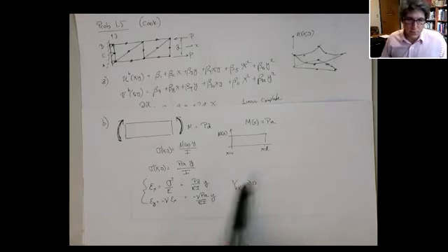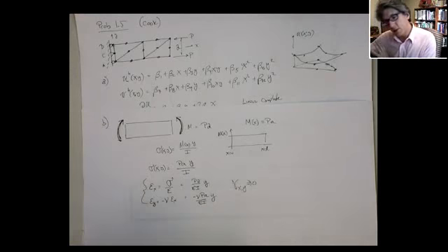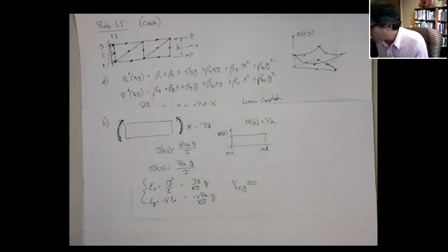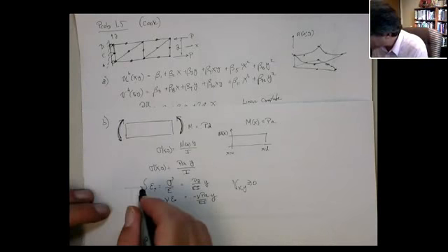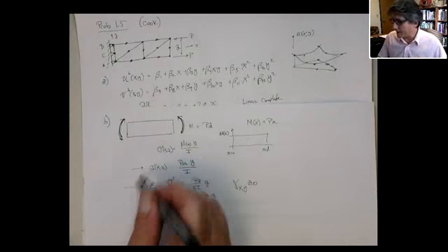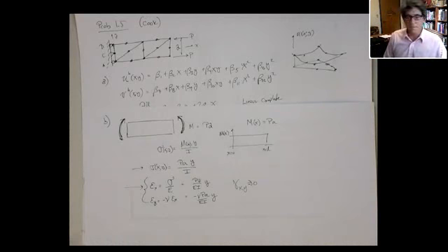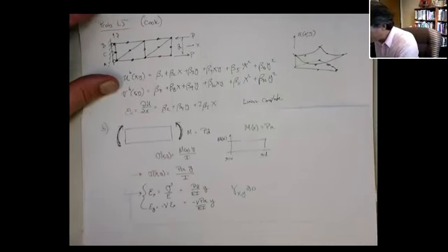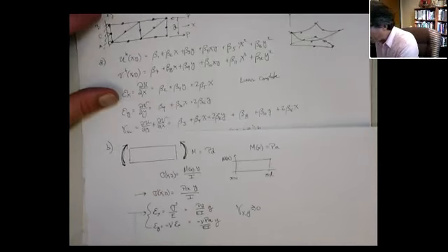That will be a little difficult to show up, but let's talk about a situation where the shear stresses nominally go to 0. They're mostly focused in this problem and trying to reproduce these bending stresses and strains. Okay? And in that situation, this element should do a reasonable job on that.